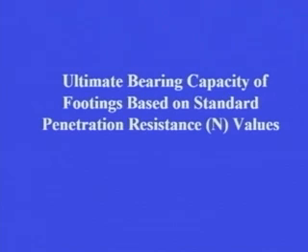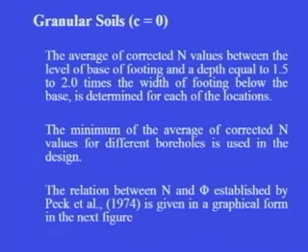So, one such method is the ultimate bearing capacity of footings based on standard penetration resistance value. As far as the procedure is concerned, that is already covered in the geotechnical exploration lectures by Professor Mahendra Singh in this series. This method is very suitable for granular soils, and mostly in granular soils the stress conditions are such that we get c equal to 0.